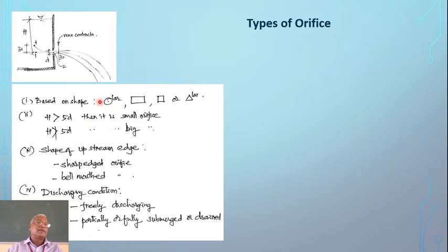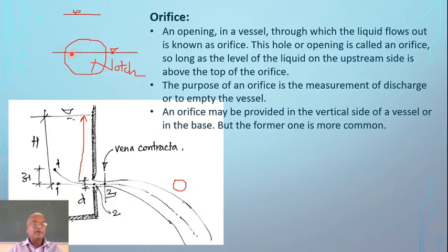Okay, here the same figure is there. What we have to observe in this figure is what is known as the vena contracta. In the earlier figure also I have written the vena contracta. If you look at the geometry of the jet that is coming out, because of the pressure from the top and from the bottom, when the jet comes out, its diameter decreases and reaches a minimum, and afterwards the jet diameter increases again. I think you will be able to appreciate this.